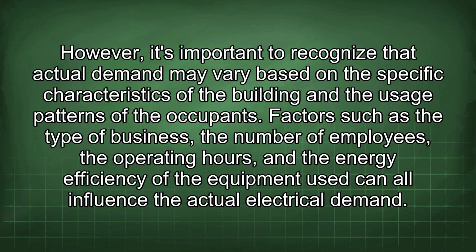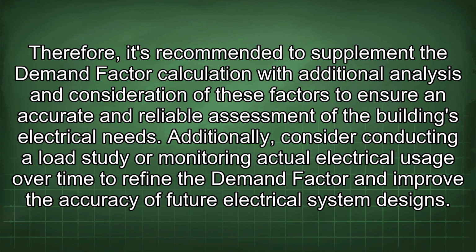Factors such as the type of business, the number of employees, the operating hours, and the energy efficiency of the equipment used can all influence the actual electrical demand. Therefore, it's recommended to supplement the demand factor calculation with additional analysis and consideration of these factors to ensure an accurate and reliable assessment of the building's electrical needs.